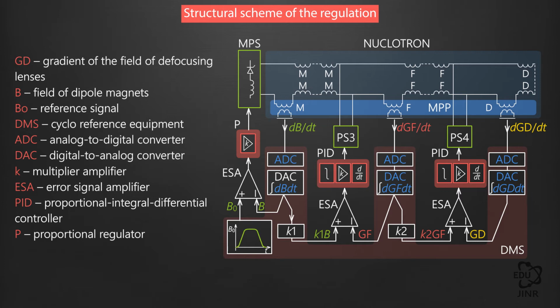Tuning is done by means of a feedback system. As feedback system signals, either an indication of the magnetic field strength value of a measured period or the readings from current sensors of the corresponding chain may be used. For adjustments, proportional, integral, and derivative controls are used, known as PID controllers, which provide the required quality of the execution of a magnetic field cycle.